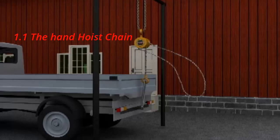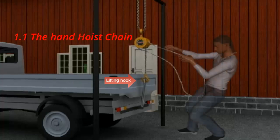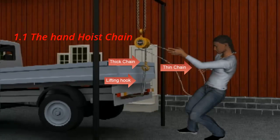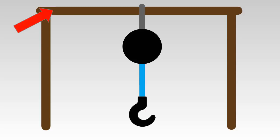This is a 5-ton chain block, meaning it can lift 5,000 kilograms. It has a very strong hook attached to a thick chain, capable of lifting 5 tons. A much thinner chain is used by a human to pull on, in order to lift the load up. To operate the chain block we need a strong support, like a tree or a beam to hang.